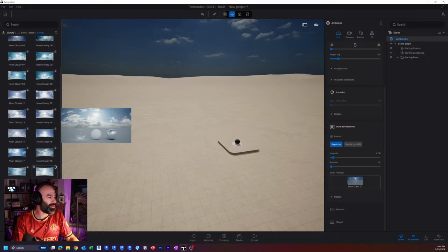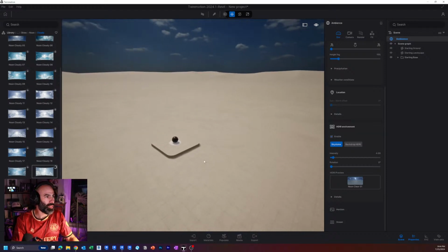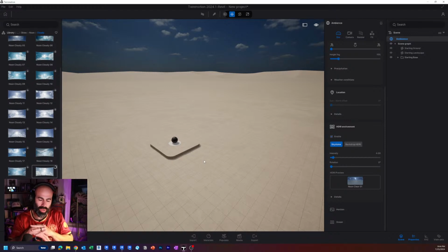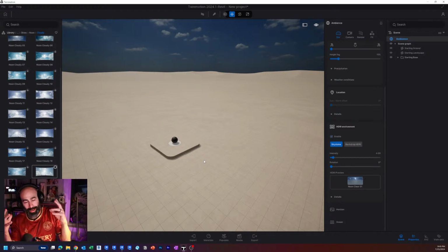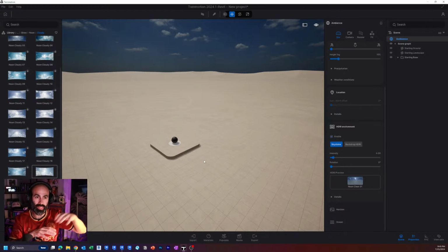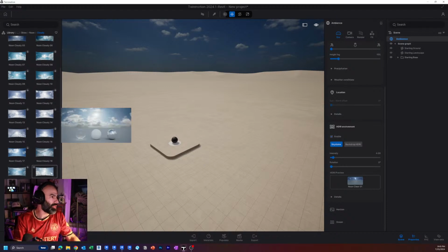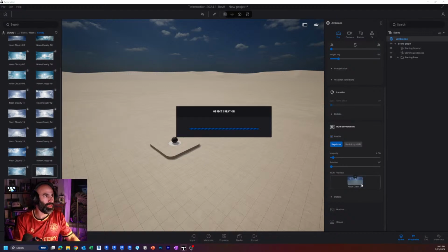even if I'm just showing you guys something good here. Okay, so what I'm going to do is load in the raw model. I'm just going to show you how those topography tweaks or topo solid tweaks make it so that you can build. This is where Twinmotion, in my opinion, excels above Enscape, is in this ability to build non-Revit context and geometries and objects quickly. Okay, so I'm going to throw noon cloudy on there.